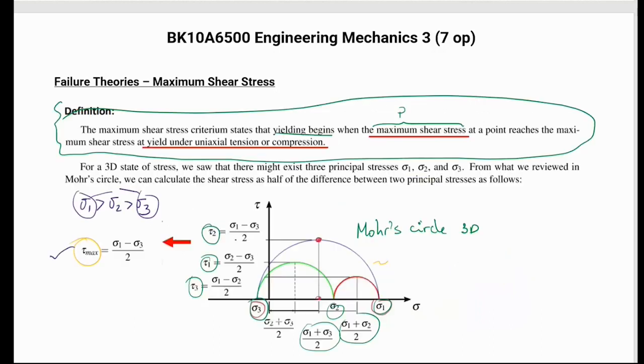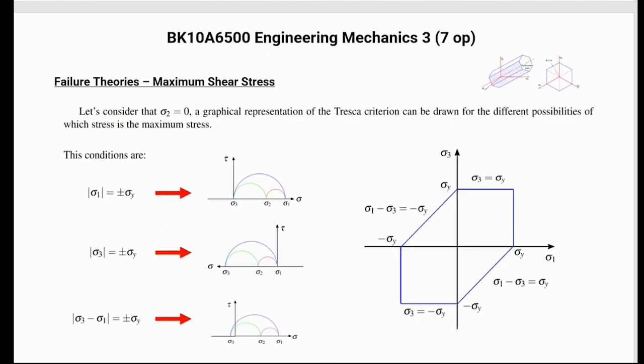Of course, there's a lot of reasoning behind this. Here I show you what happens if the loading case is totally on the positive side, what happens if it falls on the negative side, and what happens if it falls in between these dividing parts. This is the Mohr circle representation. Depending on whether it's totally positive, negative, or in between, the Tresca or maximum shear stress criterion gives you this form.